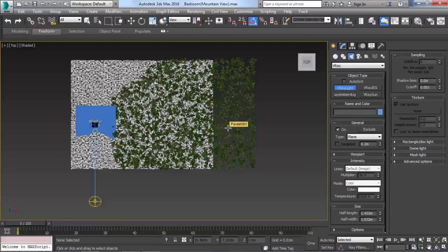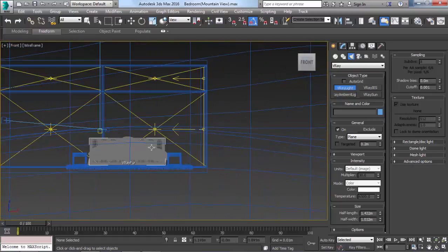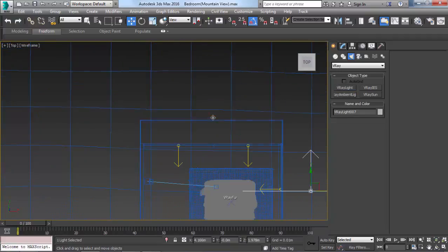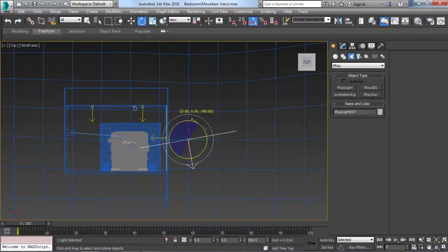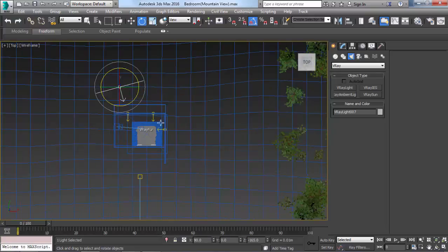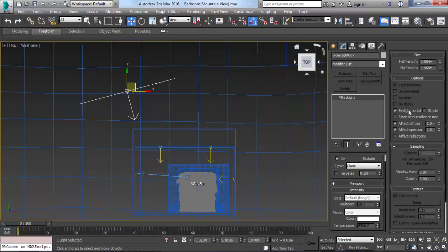Yeah, before we take a render, I want to put a light here. Where is the house here? I want to make a light outside the house. As you saw, the scene is very dark till this point. So I'll probably put this as not a skylight portal. Make it invisible. The multiplier to 300. Leave the color to white.